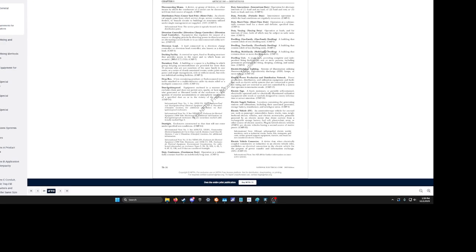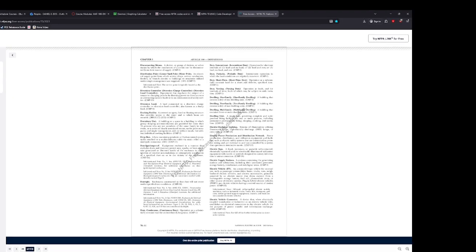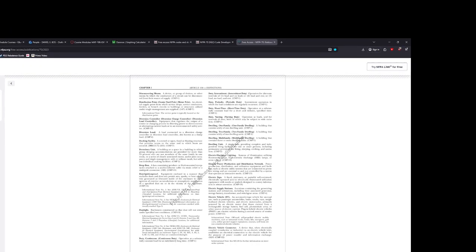Continuous duty. All these duty ones are a little tricky to remember, especially what percentages you would class it at, but that's just something you'll need to look over on your own and make sure you get it down fine enough. So, intermittent: alternate intervals of load and no load, load and rest, or load, no load, and rest. Periodic: intermittent operation in which the load conditions are regular, recurrent. So, something that's going to activate maybe every 2 hours or something. Short-time duty: operation at a substantially constant load for a short, indefinite, specified time.